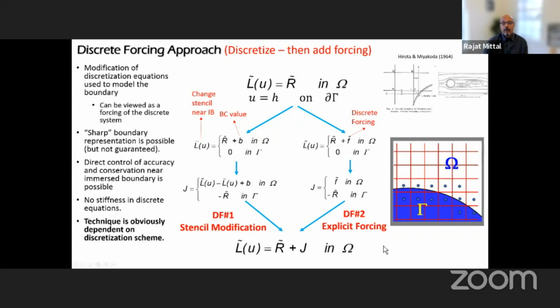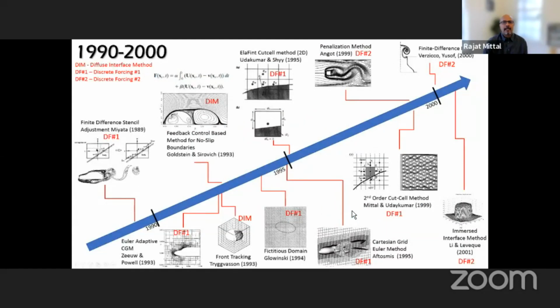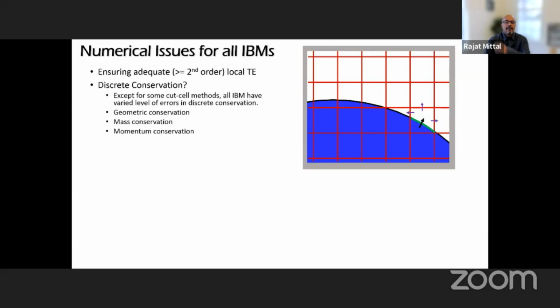But hopefully what I'll be able to show you is the advancements and the applications of this method to some very complex problems. I'm going to skip this little bit of a history lesson and continue with telling you a little bit more details about all immersed boundary methods. So with immersed boundary methods, the biggest issue is how do you apply the boundary condition at the immersed boundary and do it with adequate accuracy as well as conservation, discrete conservation.